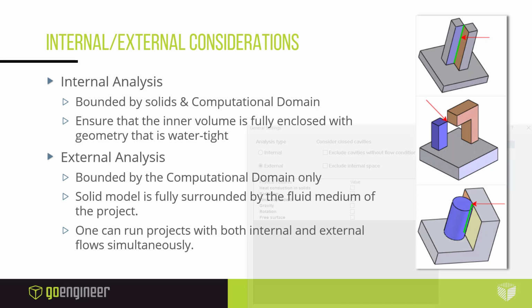A tip about enclosing these internal volumes is to look out for zero boundary thickness geometry conditions in your CAD model. Examples can be seen here to the right of this slide.